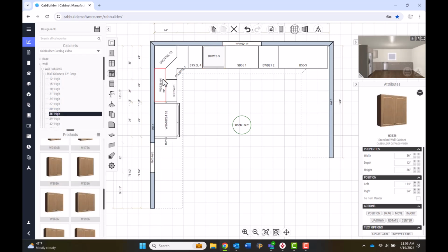If you are placing multiples of the same item, it is not necessary to drag and drop additional items from the catalog or repeat any wireframe editing if applicable. Instead, when you need a duplicate of a previously placed item, select it from the plan, navigate to the top of the design view, and select the copy icon. Then immediately select the paste icon to the right. Once paste has been selected, move your mouse into the appropriate wall zone and click to drop the copied cabinet.